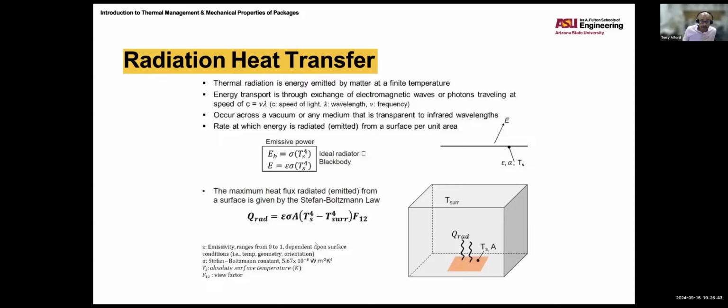And for radiation, likewise, I can get the thermal resistance for radiation. So it doesn't matter whether it's conduction, convection, or radiation, I have the resistance. When we have thermal resistances in series, we add them in a linear manner. Here's series.